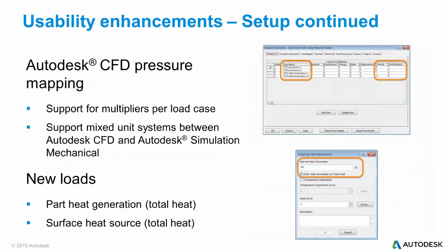Okay. Hey, Andrew, what was the question with Centroid? So the question was, with Centroid Creator, is that going to work for parts that are created in simulation mechanical, I assume by hand? And also, is it going to work with planar parts? And I think that was part of the slide there, that yes, it will work now because it supports edges. So if the model is created using any CAD package, it will work for a selected surface or a selected edge. And you can also mix and match those as well.